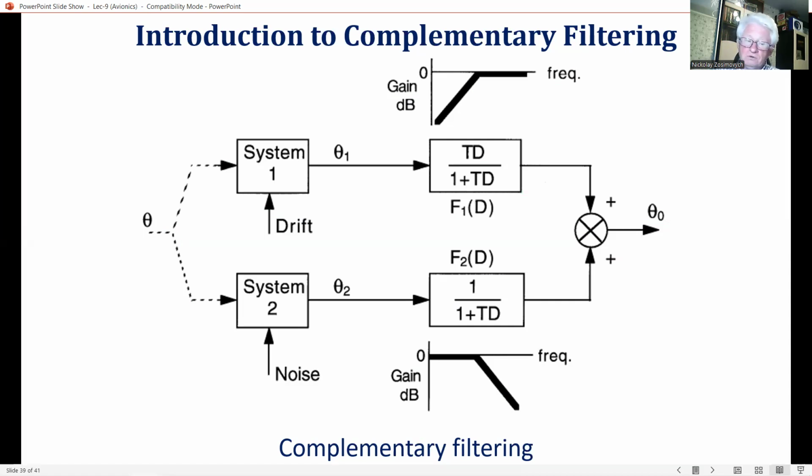Other examples include combining a magnetic heading reference with a gyro heading reference, and combining barometrically measured altitude or radar altimeter measured altitude with inertially derived altitude. Sophisticated mixing systems exploiting Kalman filters to control the gains of the mixing loop are frequently used, particularly in view of the computing power now available to implement such systems.